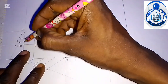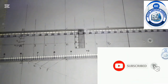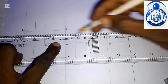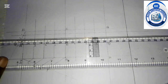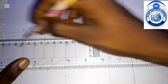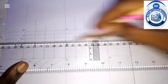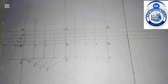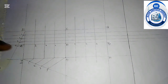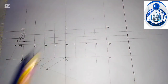So from each of these points now, I will produce a line. So let me use my T square for that to be fast. So I will come this way. So draw this, move it up to the point, draw this, then finally you have it this way. All right, now, so what I'm going to do now, just like I did here, I transfer this to this side. So I'm going to transfer this division to this side, so it's very quick that way, instead of using method of line division to divide each of the sides.